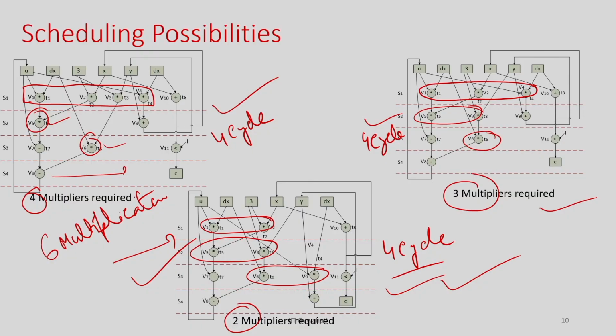The other kind of problem is that I have given you a latency bound, just like the example I have shown here, that let us say you schedule this in 4 cycles, but you identify the minimum resource. So, this is another angle of the problem. Both are important problems and we are going to discuss efficient algorithms for doing that. So, that is about the scheduling. Let us move on to the next phase.